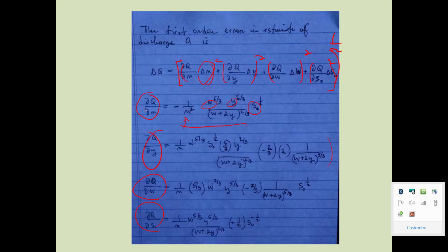You take the product of the dq/dn with the delta n, square that, and you're going to do that same thing for the other variables, dq/dy, dq/dw, dq/dz, dq/dS0, multiplying them by the errors in those individual parameters, squaring all those, summing them, and then taking the square root, and that'll give us the uncertainty, the error in the value of q.